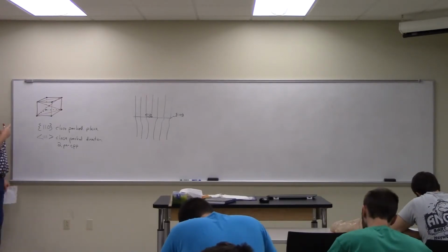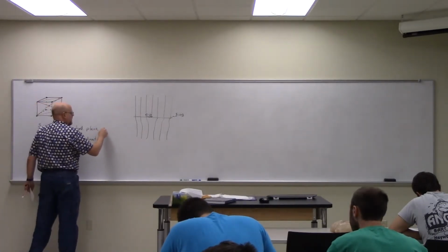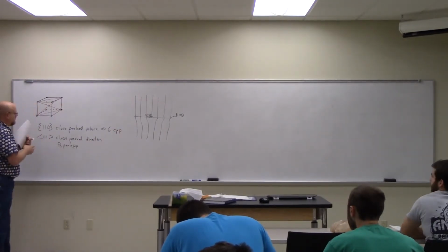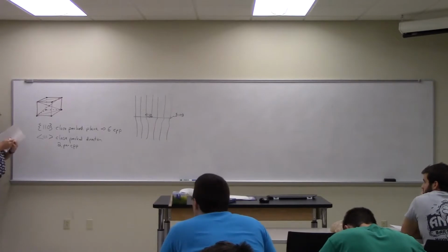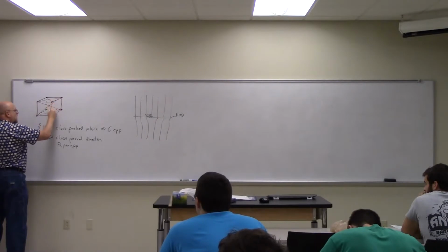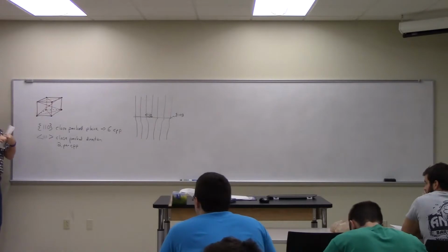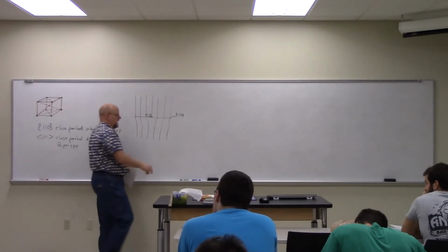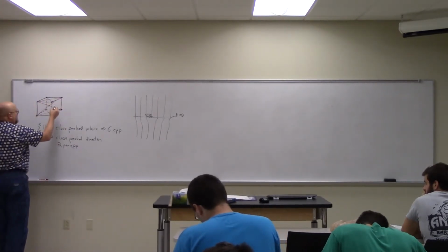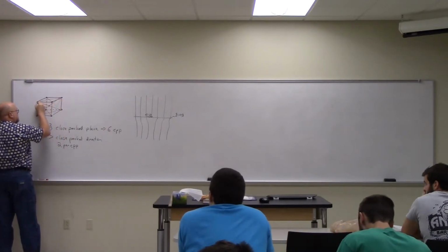And then in the unit cell, there are actually 6 close packed planes. That's 1. You see 1. Here's 2. See how that's a separate plane? And how those two basically make an X on that top face. There are also 2 that make an X on this face, which would be that one.